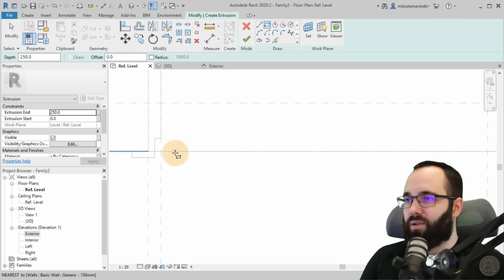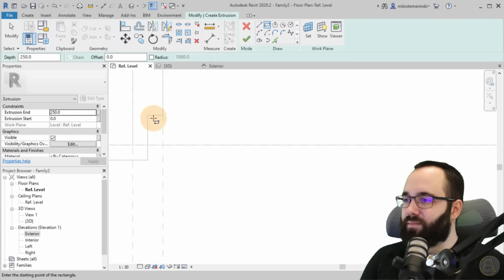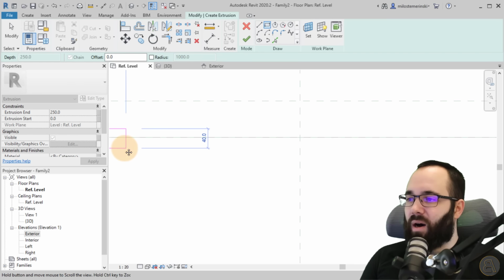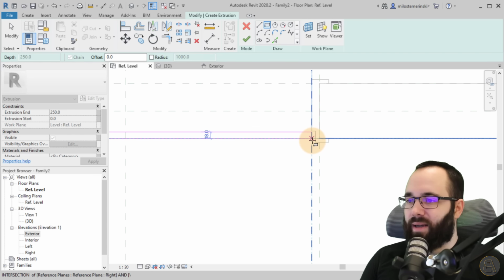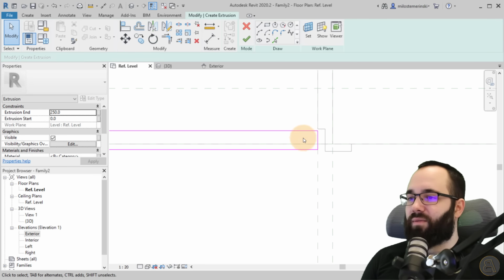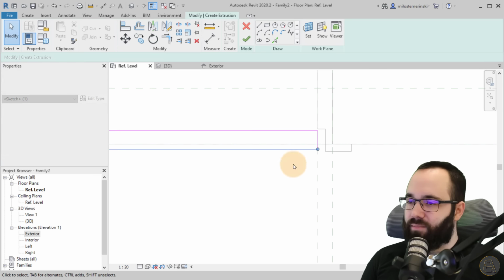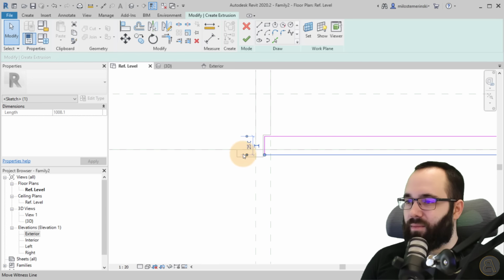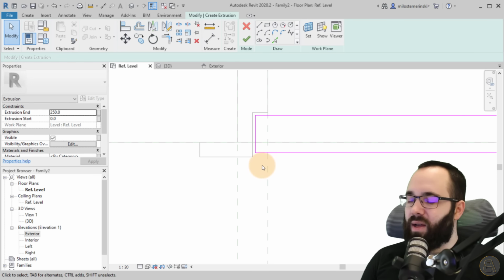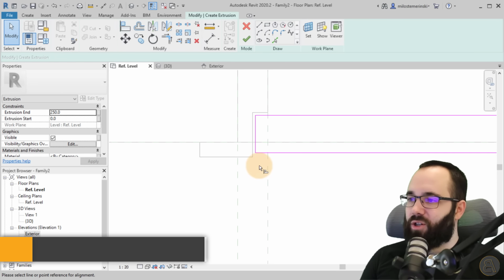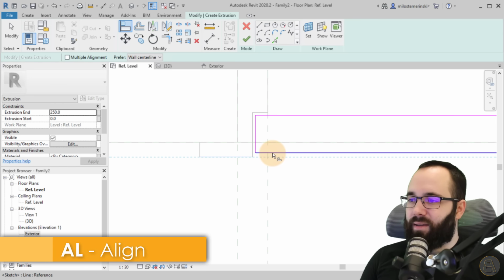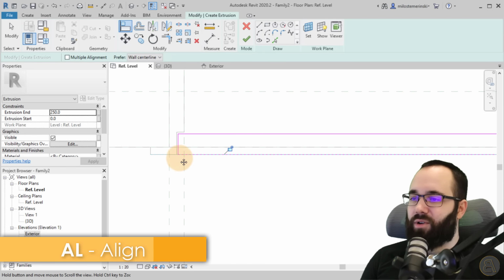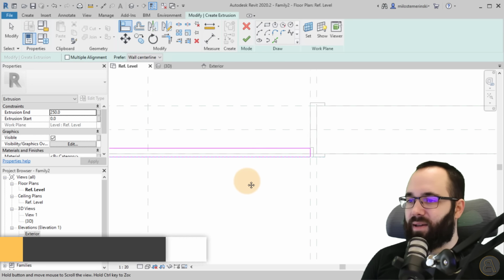So I can just go here to a rectangle tool, and then I can model this as a simple rectangle. Now I do want this to follow certain dimensions, so let's see how wide this is. Okay, this is 25. So what I'm going to do here is just make sure to lock this line to this exterior side and then lock that in place.